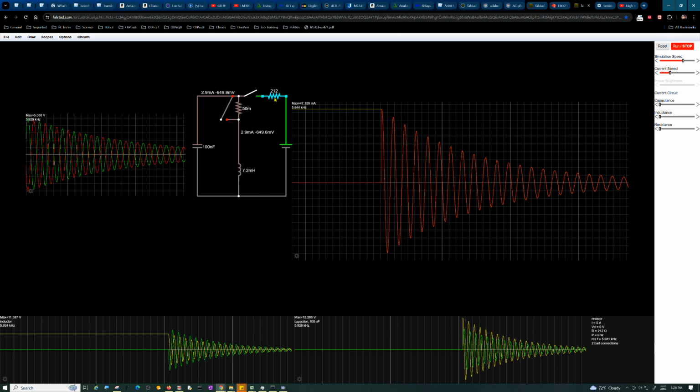And I've got 212 ohms in there to limit the current to about 47 milliamps when I close this switch. You leave it closed until that inductor charges up. So you're charging it with a DC current, and then once it's fully charged, you open that up, and that energy stored in the inductor has to go somewhere, and I have it going to an undersized capacitor here. So you take this energy and apply it to this capacitor, and it's going to generate a higher voltage than you're applying to it.